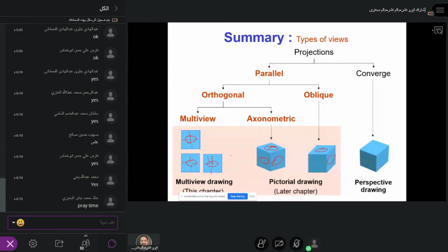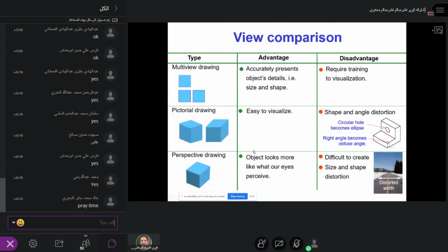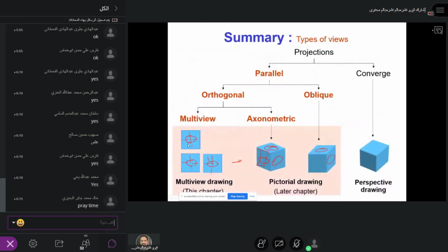We simply keep your eyes parallel to this. Exactly whatever you see, you draw it here. Then for an engineer to visualize it, he has to check these 3 drawings minimum. Of course, you have 6 views. You remember that there are 6 views possible, but a maximum of 3 views is okay. You know why? The top view and bottom view are the same. The right side view and the left side view, most of the time, if it is symmetric, are the same. So in order to keep the views minimum, we normally keep at least 3 views.